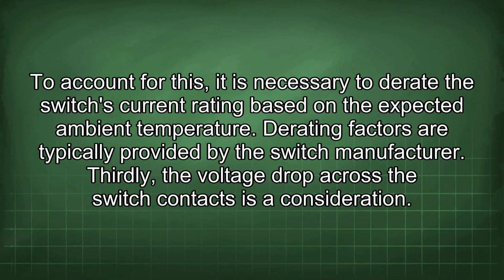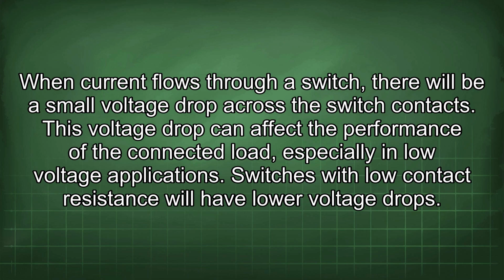Thirdly, the voltage drop across the switch contacts is a consideration. When current flows through a switch, there will be a small voltage drop across the switch contacts. This voltage drop can affect the performance of the connected load, especially in low voltage applications. Switches with low contact resistance will have low voltage drops.